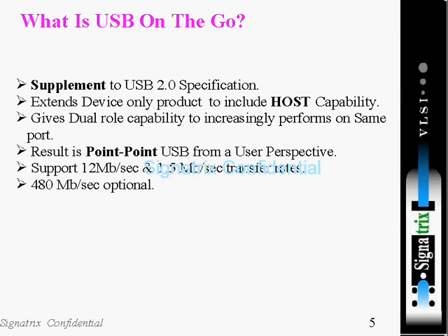Okay, so now I think you asked that question, what is USB OTG, right? I hope you are clear with that. USB OTG is actually a supplement to the USB 2.0 specification, and the main intent of this USB OTG protocol is to extend the device-only product to have host capability. So a portable device will act as a dual-role device. It will act as a device as well as a host.